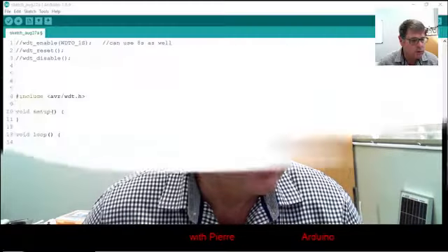Within the next few minutes you will know exactly how to use the Watchdog timer. I'll also give you some sample code that you can start off with. Now the function of the Watchdog timer is to make sure that your program is running, and as soon as it hangs, or if it doesn't reach the next command, then it will do a software reset on your program. So let's have a look at the code.